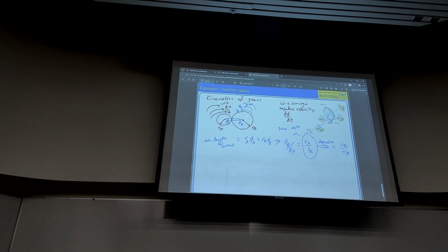All right, if now I look at the common force at the teeth, I can say the torque over radius is the common force. We know the torque is radius times force. So I can write this equation for the two.